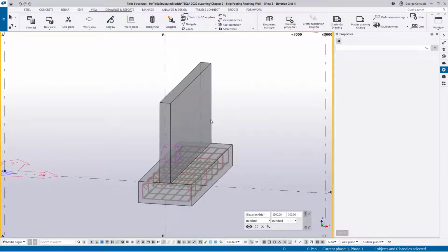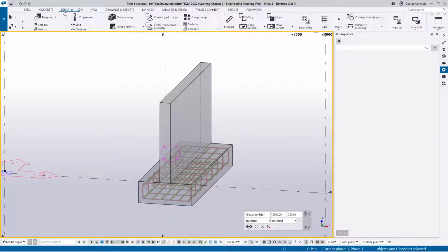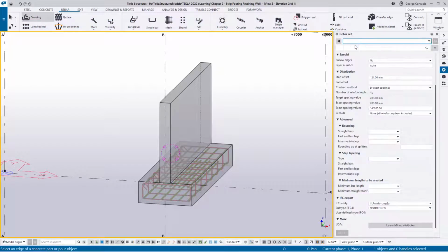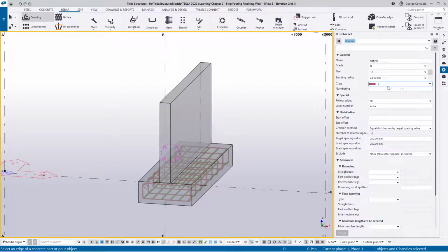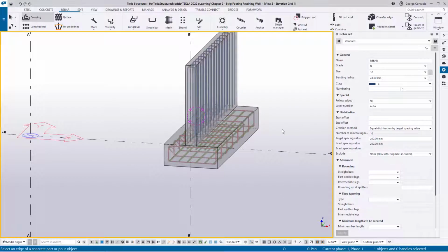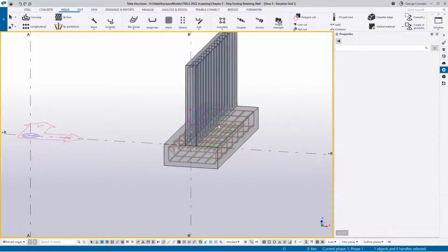So what we can do here is we can say rebar crossing bar, and make sure that I load my standards just to make sure everything is set to defaults again. And again, I'll just change my color to a class 4. I'll keep it as is for now. I'll hover over the wall shape, and this time I'm going to pick only those 3 legs and leave it open at the bottom and say OK. And now we've got a big U around the top of the wall.